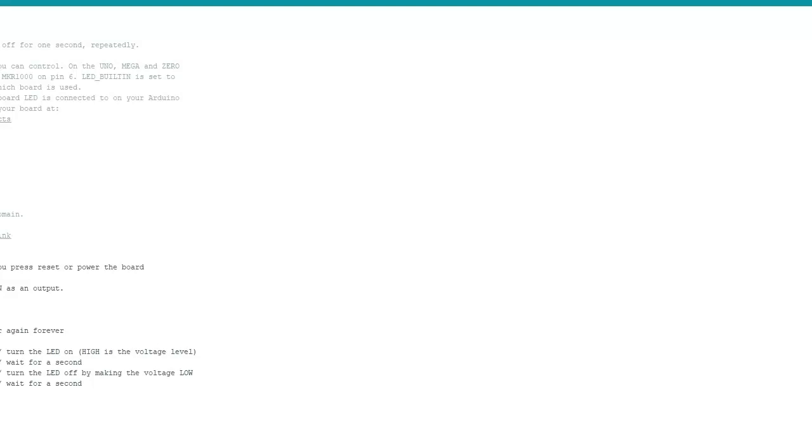Once I'm done compiling, I need to upload this program onto my hardware, onto my Arduino. So I would click Upload. Once I'm done uploading, I see a message down here that says Done Uploading. So then I know I am good to go.